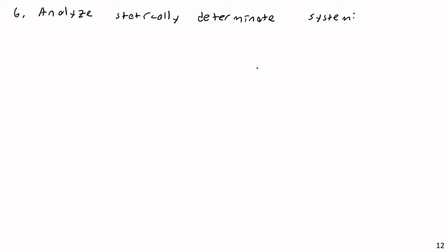So finally, my last step, which can be a bit long, is going to be to analyze the statically determinate system. And after this, we're basically done with the force method, but I'll continue working through the problem until I solve it, just so you can see what we would do. Once you've removed that redundant reaction, that redundant support, it's just another load in the structure.